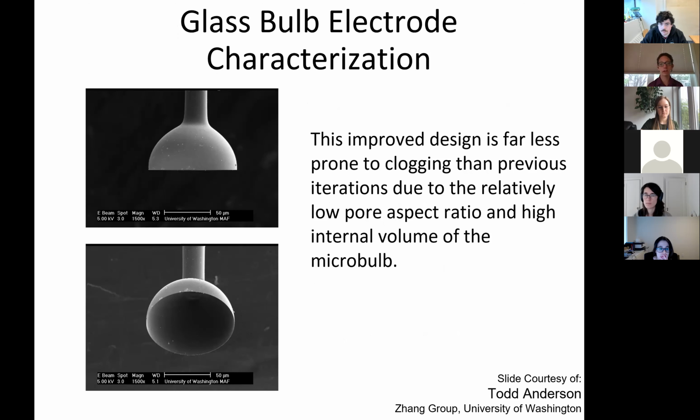But of course, we're a characterization lab, and so although he's highly focused on the fabrication side, he's taking these pores and actually looking at them in our SEM by using the FIB to cross-section them, and then able to analyze exactly what the surface area and aspect ratio of these pores are, in order to understand exactly how this electrochemical process is happening and have a very good understanding of the nanoparticles.